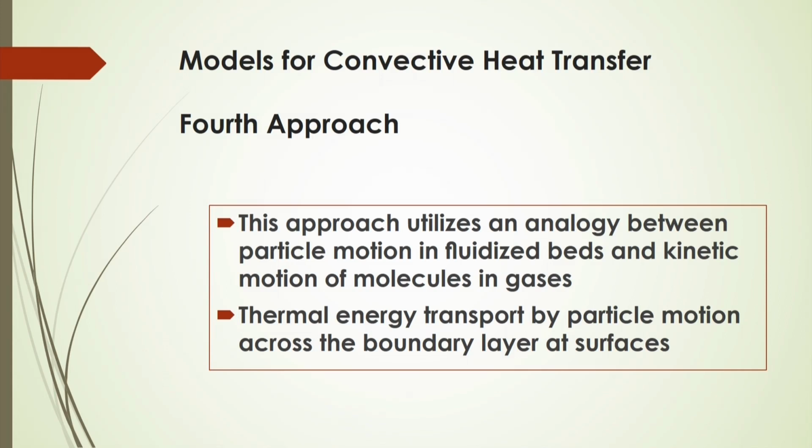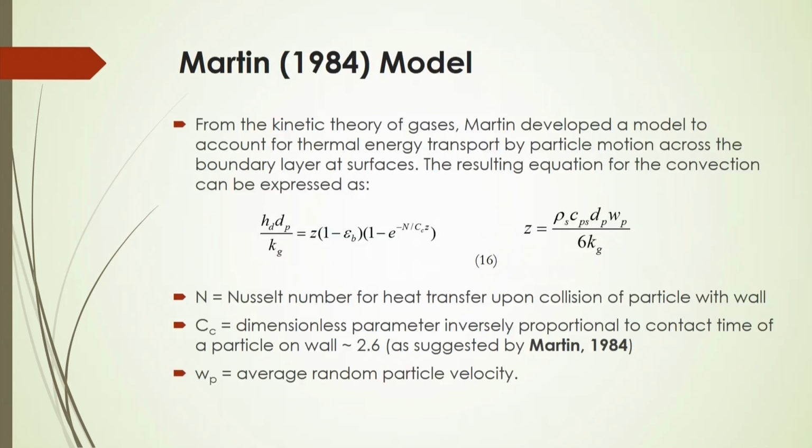Now, as a fourth approach, we can calculate the convective heat transfer coefficient. In this case, it utilizes an analogy between particle motion in fluidized beds and the kinetic motion of molecules in gases, and also thermal energy transport by particle motion across the boundary layer at surfaces.